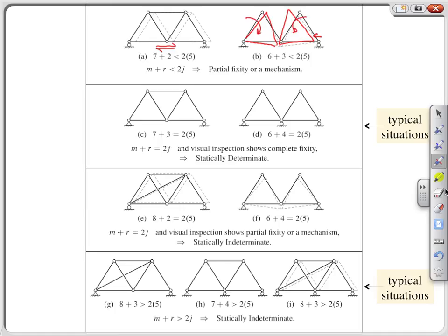Note that the sliding left of the rightmost support does not violate the roller boundary condition, because that only provides a constraint normal to the supporting surface.